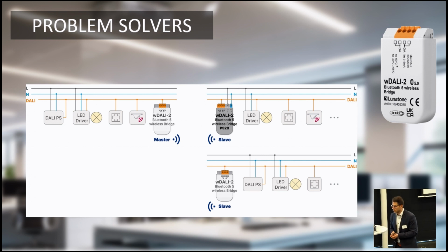If you have a DALI installation and you have one part at a distance where you are not able to put cables, or you don't want to, you can use those bridge units to have one part done wirelessly and bridge it to the extended installation.